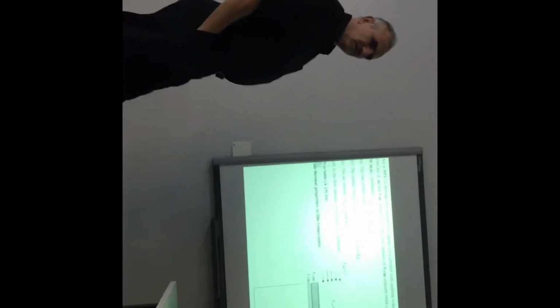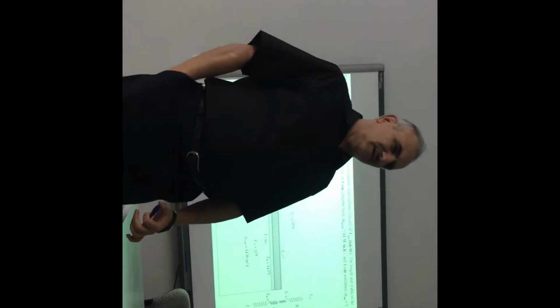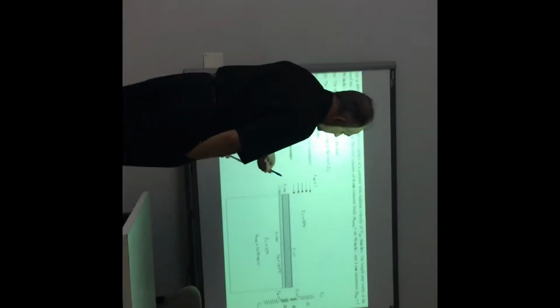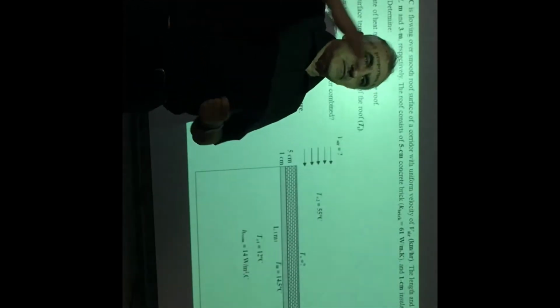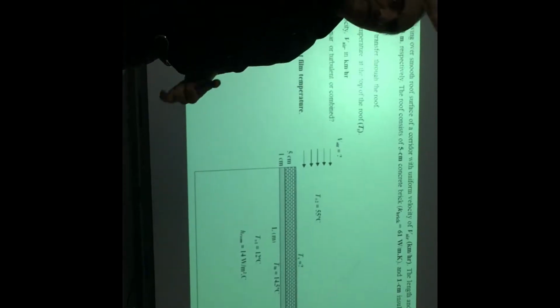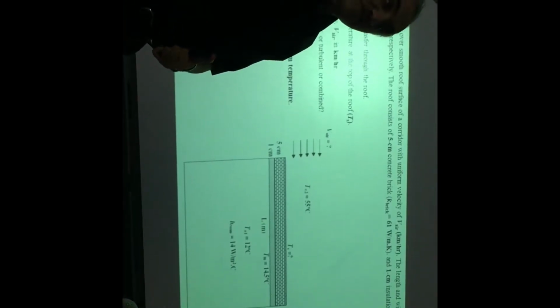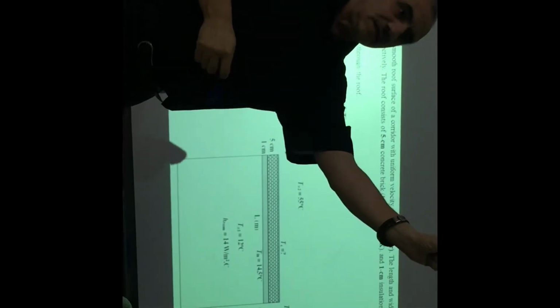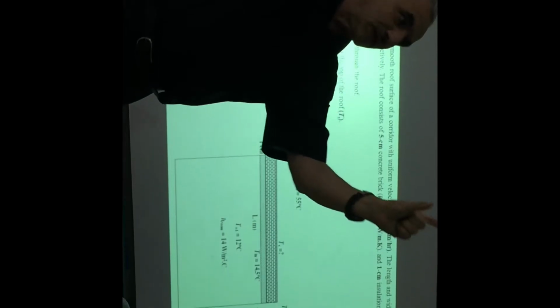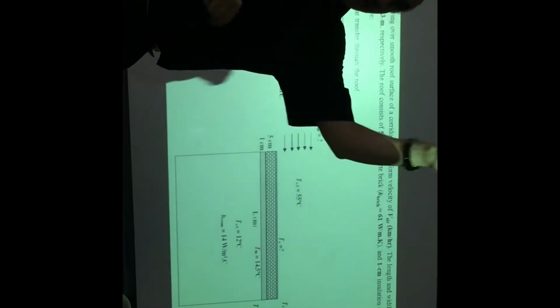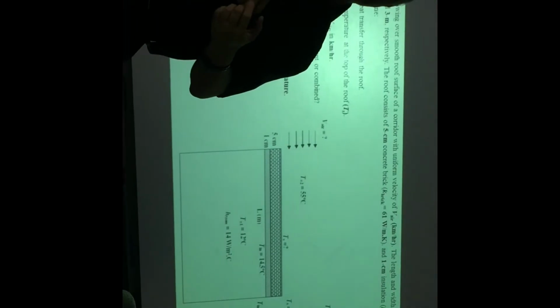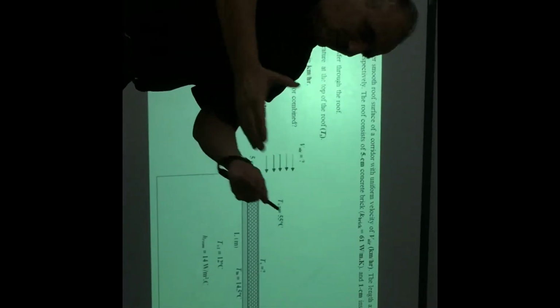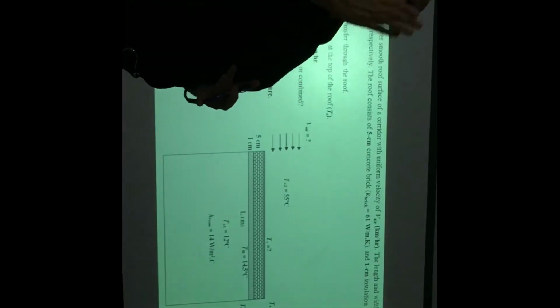Doctor, we don't need to do an interpolation in the table? No, you do, of course, if the temperature requires it. Because look, you have first to go to the table of the properties, right? In the table, is it 5, or 10 degrees, or maybe 50, for example. At 20 Celsius, this is the property. Then at 70 Celsius, this is the property. This is a big difference. Here you have to make interpolation. But if the temperature becomes 69 and you have 70 and 20, 69 is close to 70. You don't need to make interpolation. You have to judge this.